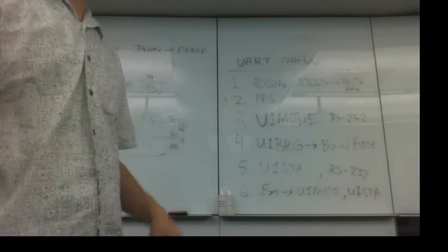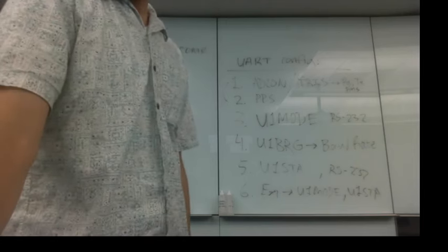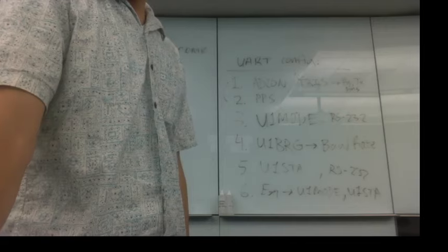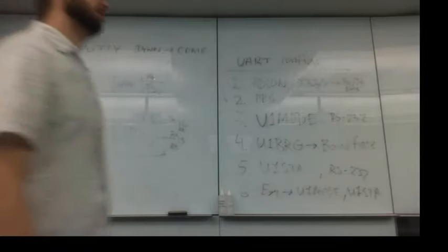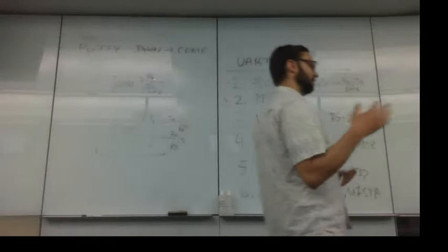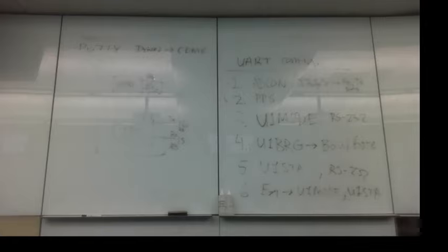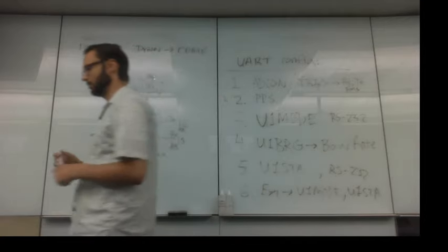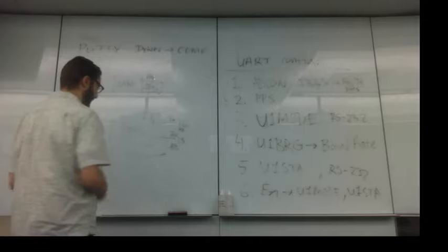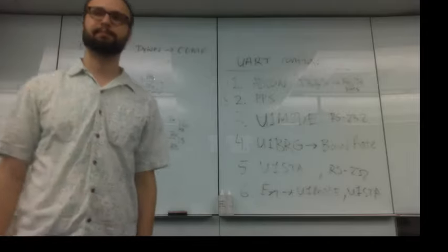So it sends it out on the UART's pin. So mode 0-0 is kind of like mode 1-0, but it's basically if you're using more than 1 byte in the buffer at once. It'll set the interrupt no matter what. Basically, it'll set the interrupt every time you send a byte out.